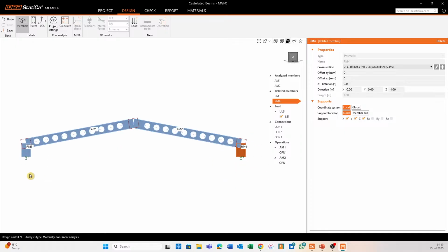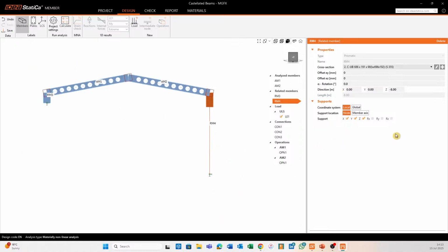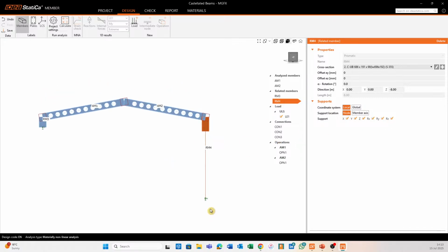So ended, of course, because these are rafters, so they're not cantilevered in a sense, but if we have to take the rafter away, these columns would be cantilevered, all right? So just the bottom is connected. In the direction, I want to set the height of that column, so -8. You can see that extends there, and I want to add that it is a fully fixed support.